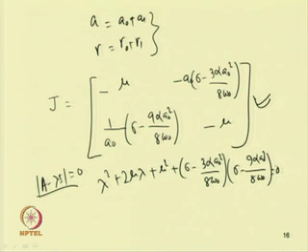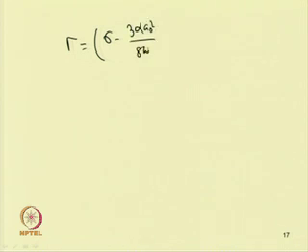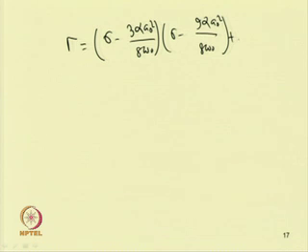So, the steady state motion will be unstable if we have this term, sigma minus 3 alpha A 0 square by 8 omega 0 into sigma minus 9 alpha A 0 square by 8 omega 0 plus mu square, less than 0.